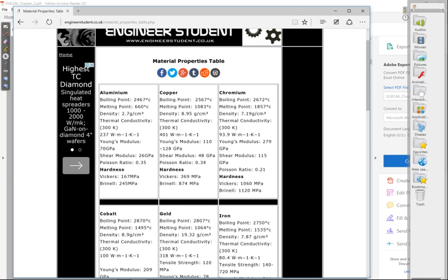That amount of thermal conductivity, and this is the one that we really want. Young's modulus, 70 gigapascals, is the typical Young's modulus for aluminum. Now, obviously, there are different alloys of aluminum, and these properties are going to differ a little bit between the different alloys. But this, I would imagine, is pure aluminum.